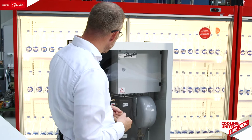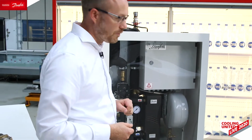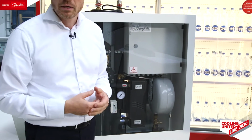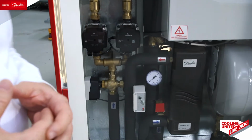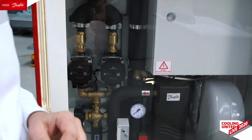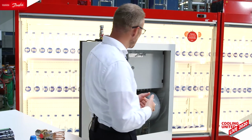The specific system here has variable speed pumps to provide the flow to the system. And it also has the three-way pump shunt to make sure that the right temperature is always provided to the system. So the task of the pump shunt, and the pump station, is to provide the right flow and the right temperature to the cases.